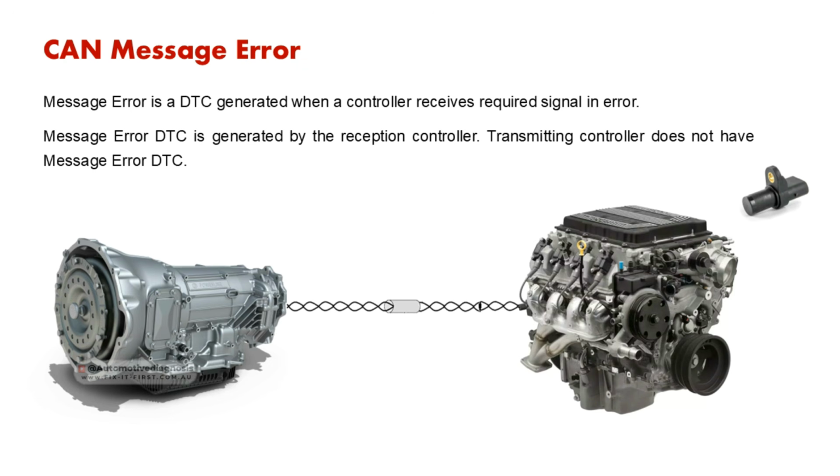Sometimes it's not going to point exactly to the engine RPM, but if you check the ECM with a scan tool, you may get some fault code related to the crankshaft position sensor. So once you fix the crankshaft position sensor, that fault code in ECM can be erased. And of course, the other faults on the other control units will be erased as well, because there is no invalid data anymore.